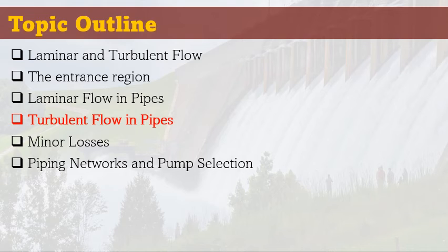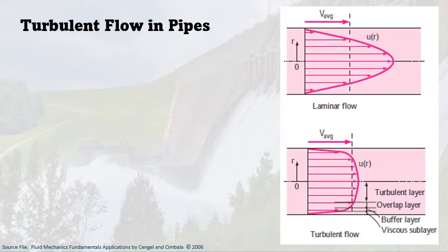Now that we already know how to compute the different quantities in laminar flow in pipes, we are ready to dig deeper into turbulent flow in pipes. Most flows encountered in engineering practice are turbulent, and thus it is important to understand how turbulence affects wall shear stress. However, turbulent flow is a complex mechanism dominated by fluctuations, and despite tremendous amounts of work done in this area by researchers, the theory of turbulent flow remains largely undeveloped. Therefore, we must rely on experiments and the empirical or semi-empirical correlations developed for various situations.